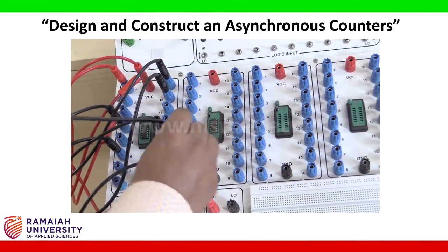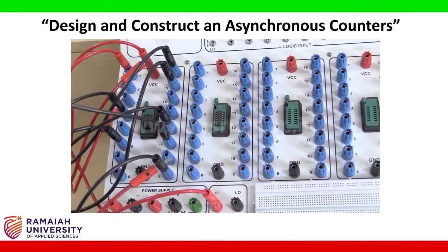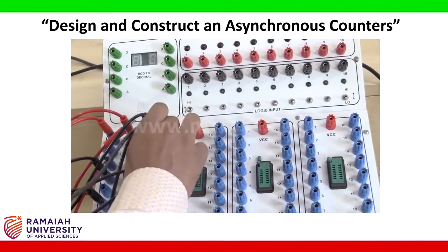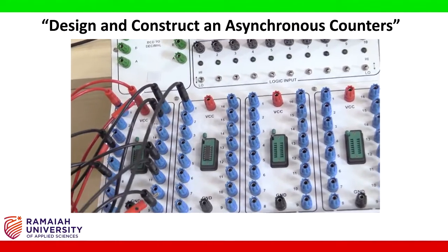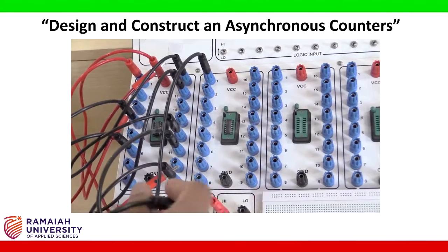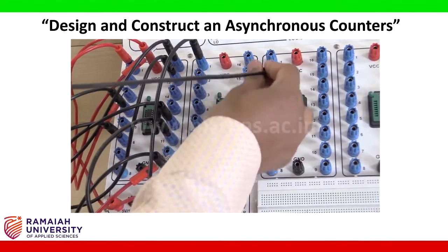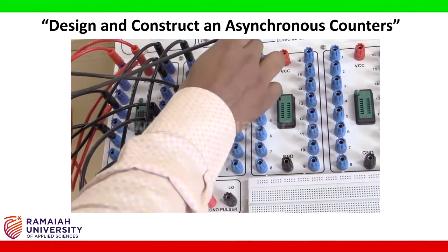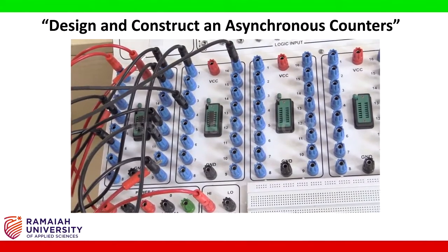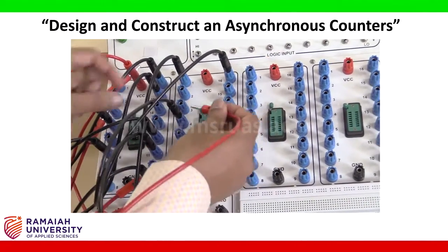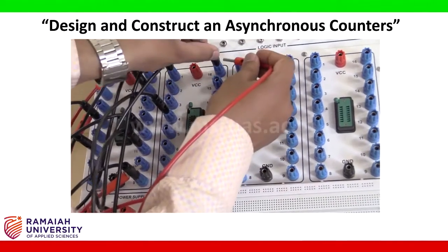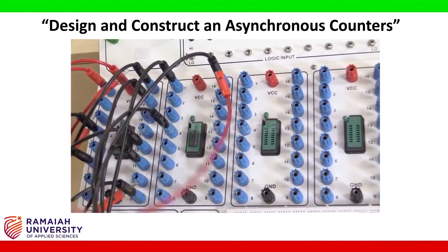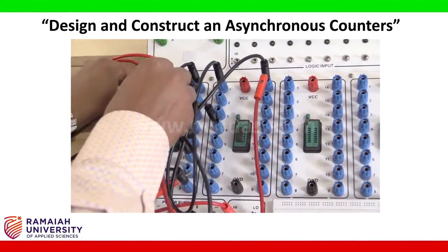Then pin number 11 is connected to pin number 1 of the second IC base, that is 7476 IC, and pin number 4 and 16 of the second IC base are shorted, and from that it is connected to VCC here.